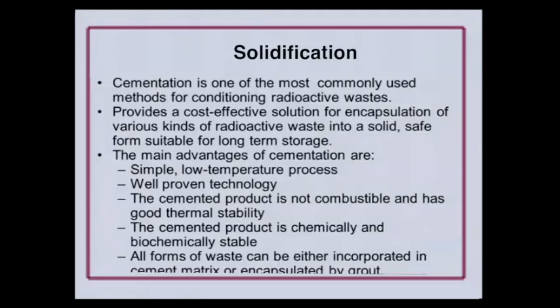It'll stand heat for extreme temperatures. It's chemically, biologically stable. And you can either mix it in with a matrix or you can encapsulate it by grout. The grout method is what's being used to stabilize the tanks out there at the site. And the grout is nothing more than kind of a soupy cement mixture. And it's really used to do the final step in closing out the tanks out at the site.